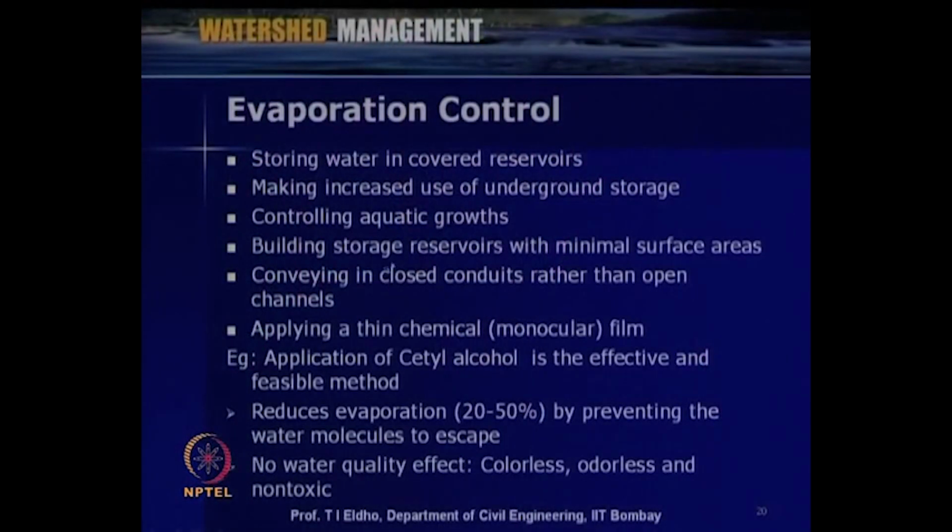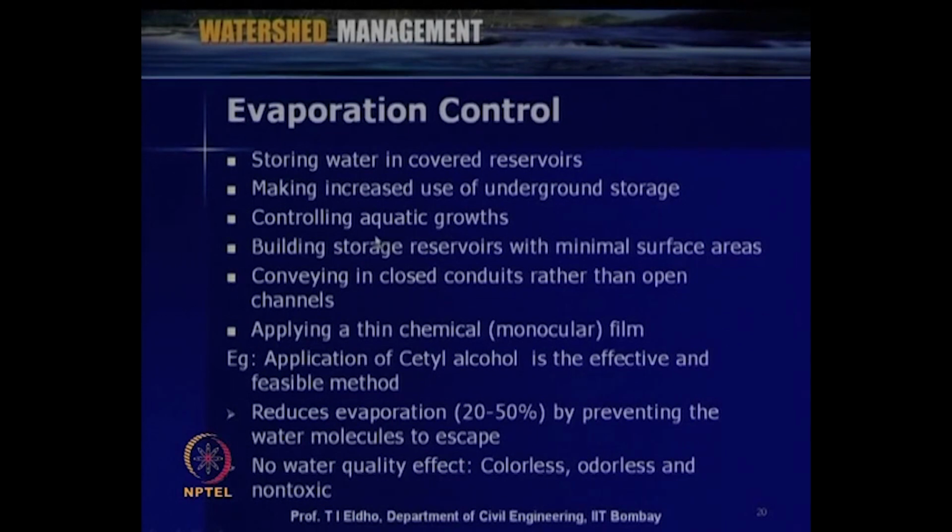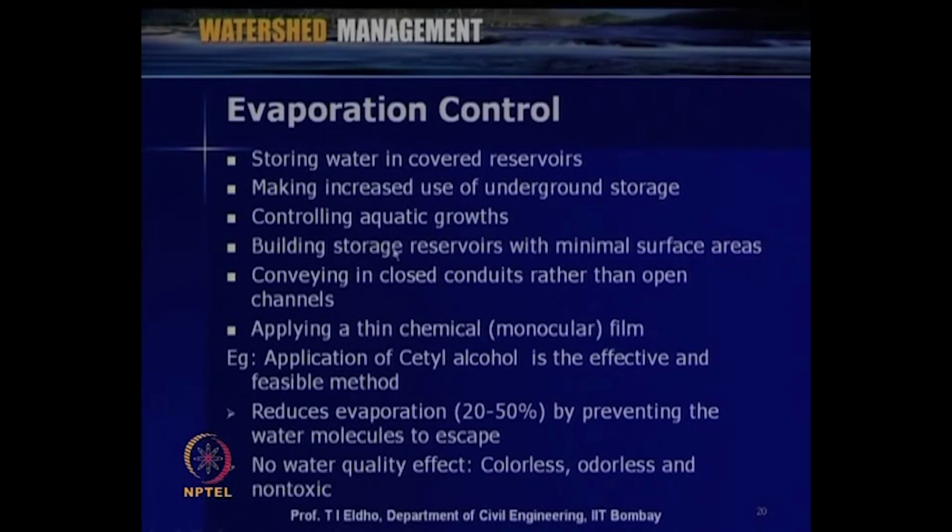Here I have listed various evaporation control measures, like storing water in covered reservoirs, making increased use of underground storage, controlling aquatic growths, building storage reservoirs with minimal surface areas, conveying water in closed conduits rather than open channels, then applying a thin chemical or monomolecular film, like by using